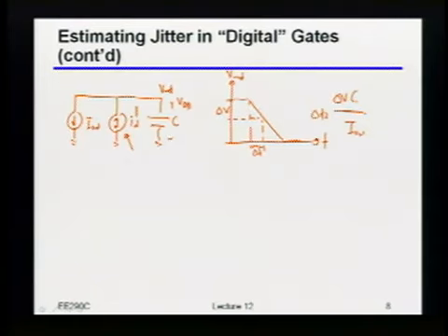So what we're starting to get at now is that if I want to figure out the impact of that noise current, which as we've been saying is going to add some fluctuations on top, it looks like we have to do this sort of windowed integration of the noise current, right? In other words, we have to integrate from some 0 time to the nominal delay time and figure out the expected variance in the voltage due to that, right? So we can indeed do that. I'll show you a little bit how you can do it in 1 second, but it turns out there's a little bit easier way to think about it, okay?